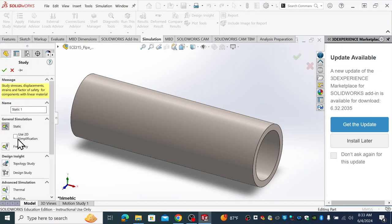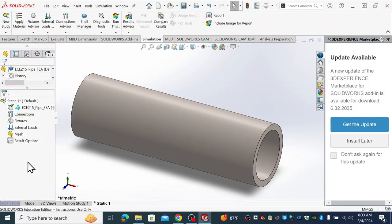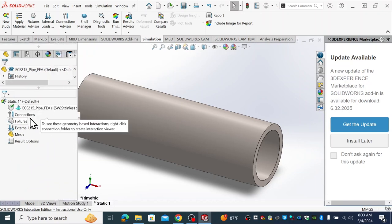I want to do a static study. There are a lot of other studies, but I want to do a static study. Enter. Now I have different steps. The first one is the materials, and we already have the materials. Connections is when you have multiple parts and you want to add screws, springs, things like that. We don't need that. We will start at fixture.